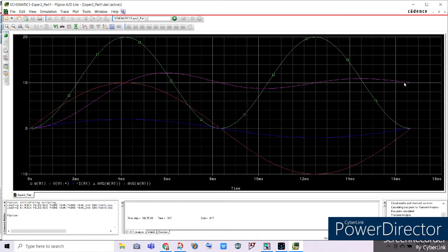The output waveform is notably different from our instantaneous power output waveform because average power is derived by multiplying the RMS value of our current and voltage, compared to our instantaneous power, which is the amount of power given at a specific amount of time, which can be derived by multiplying the normal values of the current and the voltage.